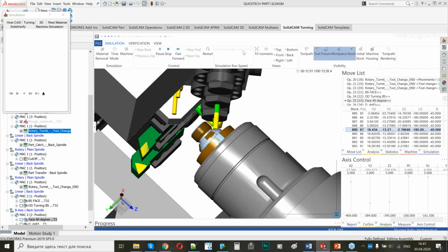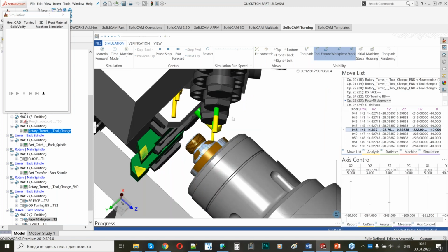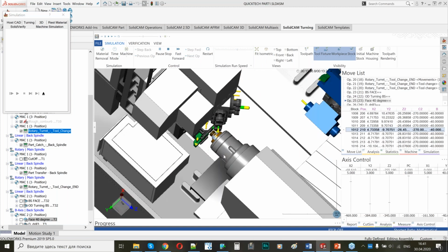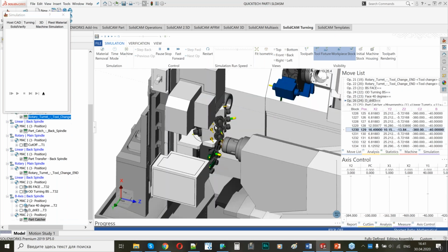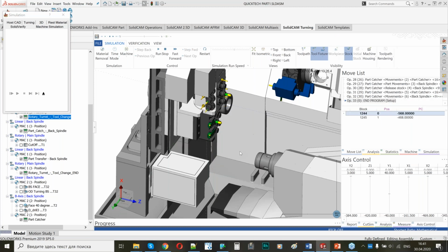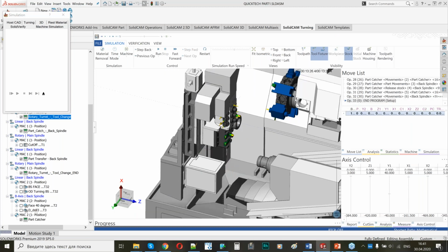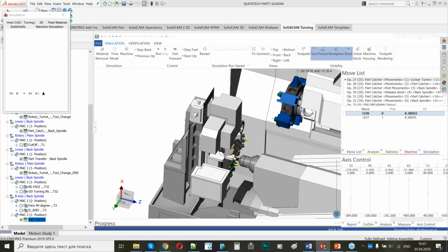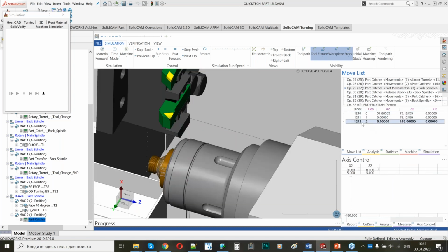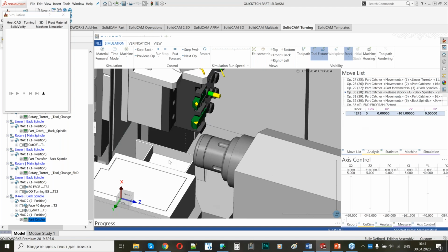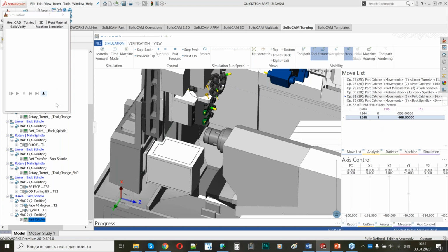This is milling. So this is how movement is performed. We have the Y movement of the gantry, and Z, X and C movement on the back spindle. And I had my drop operation here. After the drilling was performed, I put my part to the part catcher. Okay, it looks not bad.